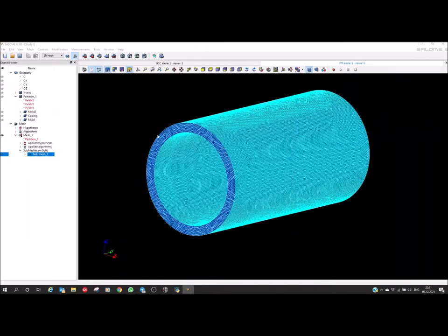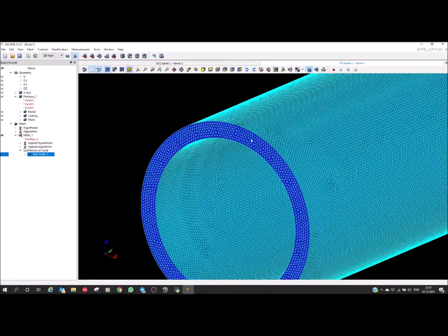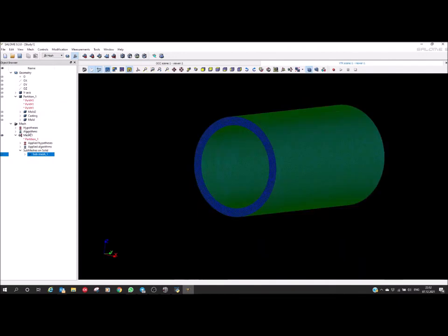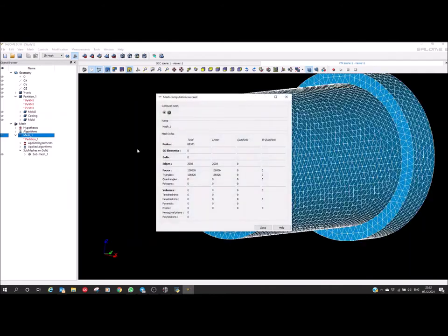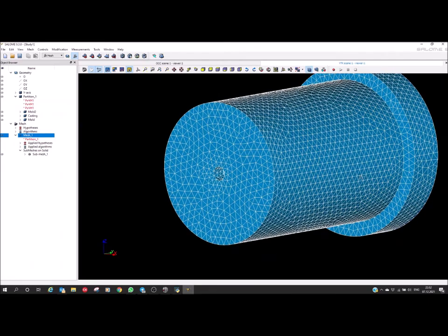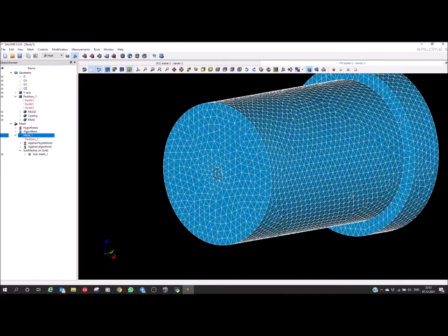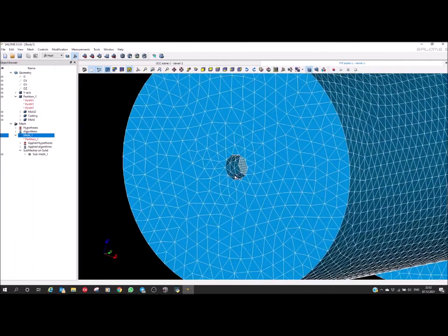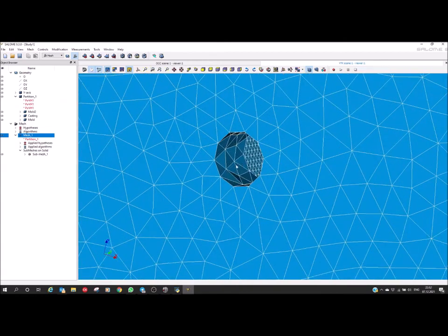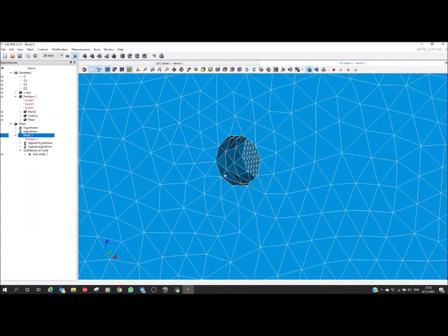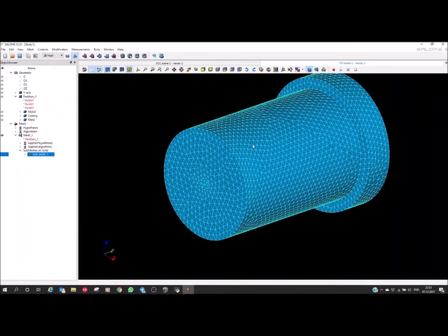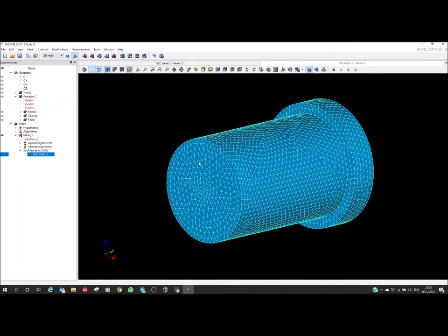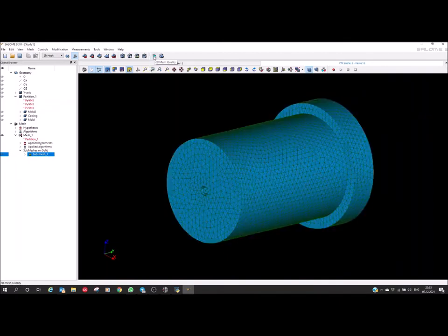It's okay. Now it looks good. And now I will compute all other elements. I think it's enough because here is 1, 2 and 3 elements. It's okay. And now I will create the 3D mesh, but first of all I will check my 2D surface mesh.